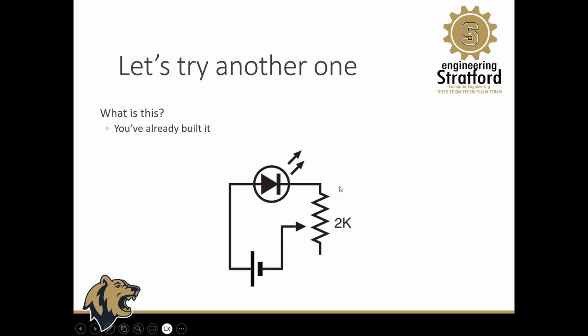So the third thing looks a lot like a resistor, a 2K ohm resistor. But if that's a resistor, there's nothing connected on the other end. But check this out. Remember how there is a little arrow coming into one of those resistors? Do you remember what that was? The circuit that you've built here was our potentiometer circuit. So that's the pot. And so in that case, we've got the 3 legs, one leg that's connected to the LED, one leg, the wiper, that's connected to the battery, and then the other outside leg that's not connected to anything. So sometimes you actually have a pot that is connected with all 3 legs, but in this case, only 2 are connected. And the wiper would always have to be connected.